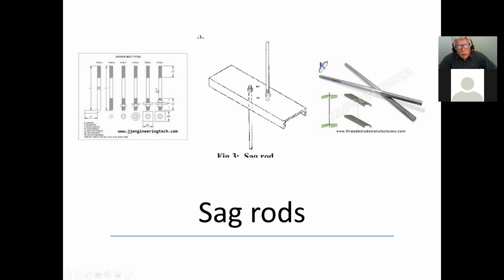So they're regular steel rods that are threaded at the ends, and of course you can put a washer and a nut, depending on the size of the hole, and you use the threaded part to be able to lift. Of course, you put one on one girt. If you have a series of girts, then this one would go and support the second girt. So the second girt gets supported up to here, then this is transferred here, and this gets transferred to your perimeter beam. That's what this is showing you here.